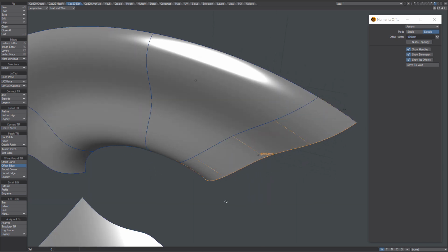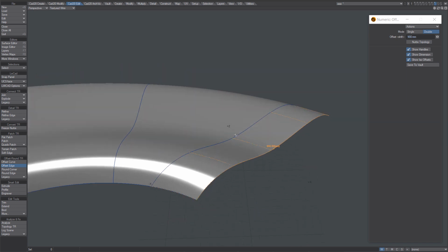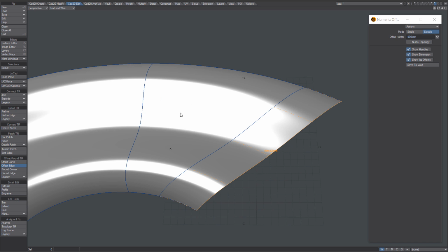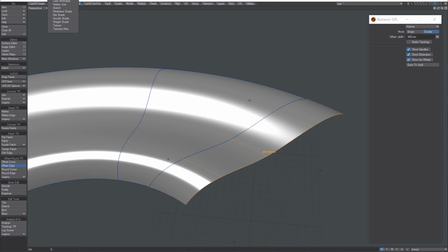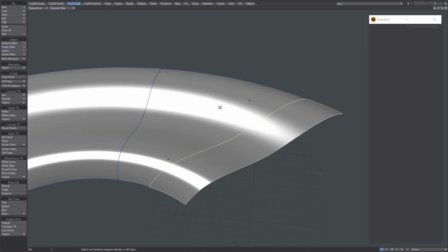Standard CAD applications do this: once you do an operation like this, the whole NURBS surface is no longer able to be edited. You cannot modify control points. It is grouped into some surface, and you no longer have access to control points. And these edges are oversampled, of course. So LightWave is much cleaner, and you still have the benefits of a small amount of control points, and you still get two NURBS surfaces after the operation, and you can still edit these control points like on a regular simple NURBS surface.